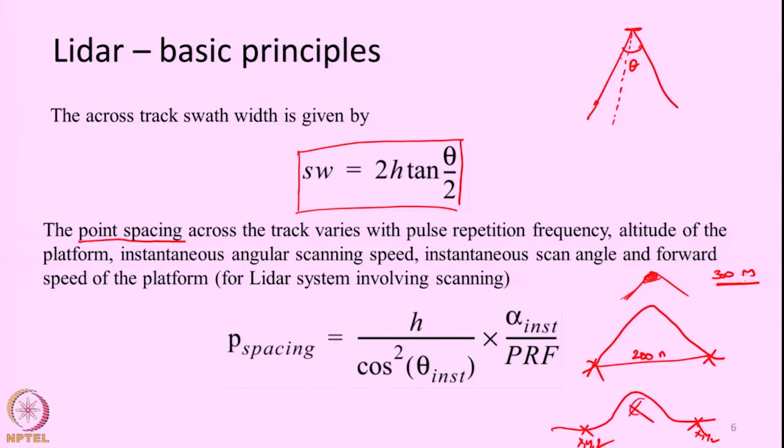When we process these xyz points, we will join them using some sort of interpolation mechanism. Then our interpolation mechanism is not going to reproduce the mound or the small hill in between, it is going to interpolate it like this, point A, point B, the mound is missed.